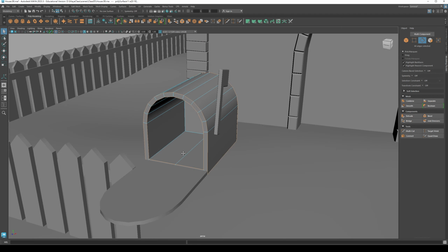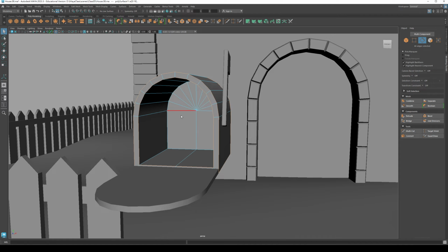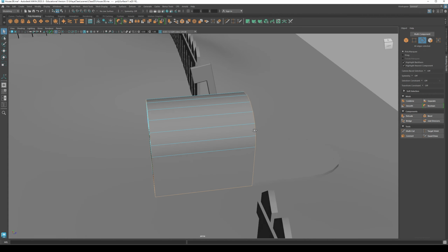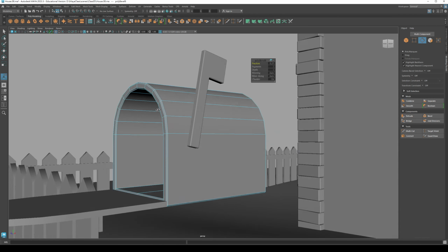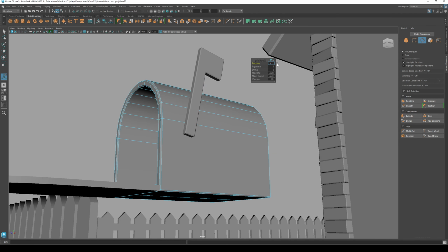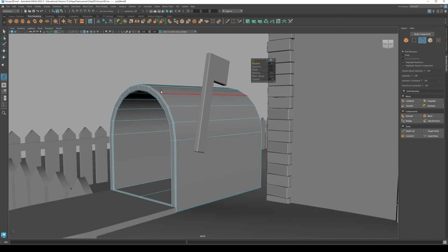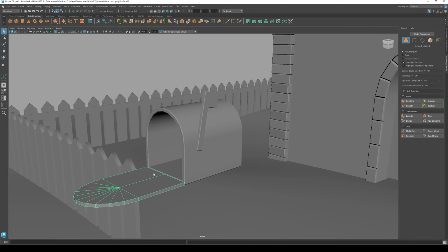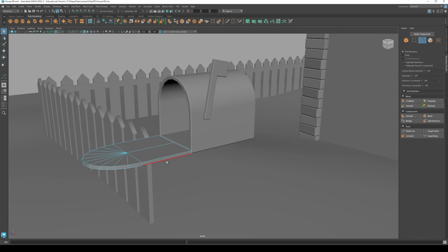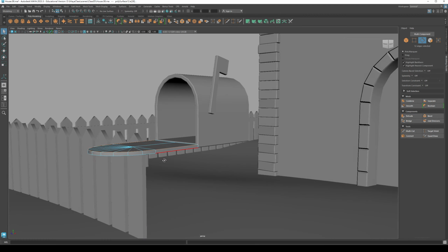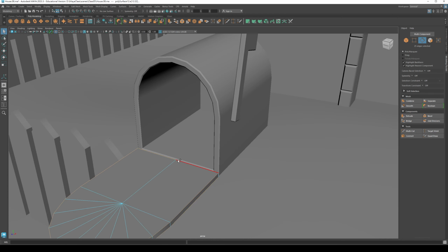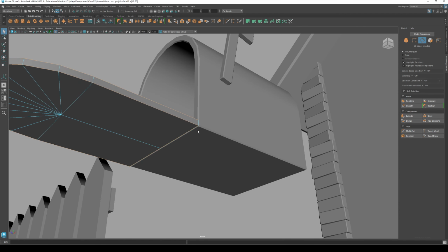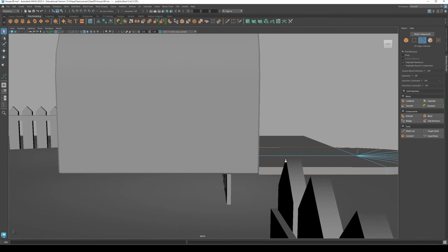Yep. We'll skip the inner part and just add bevels outside. And give the bevel. Put 0.35 or 0.3. Okay. Looks much better. And do the same thing for this part. Here. Here.